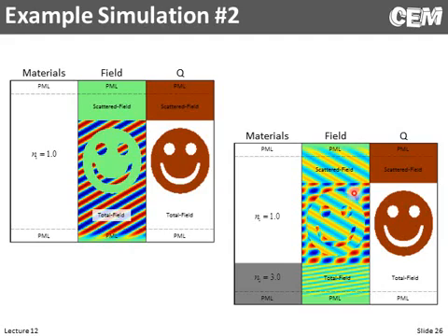But what's neat about this equation we have is that we can arbitrarily shape our total field and scatter field very easily and tie it all together with one simple equation. Another thing I'm not mentioning in here, but is very cool, if we went to higher order accurate derivatives, 4th order accurate, 6th order accurate, so our finite difference equations now couple a point in the grid to somewhere way off, maybe even 2 cells away, that equation still works.